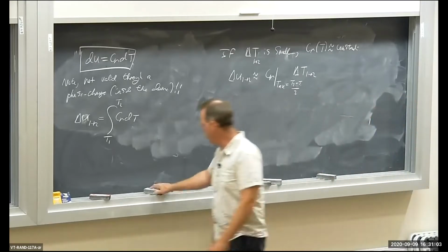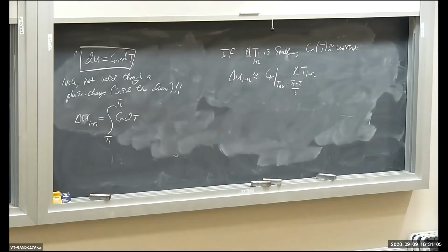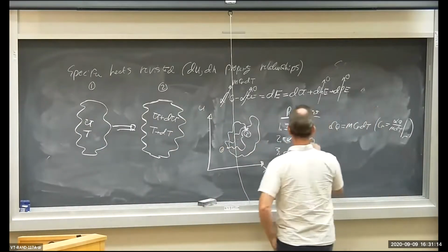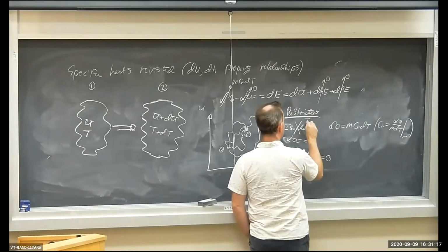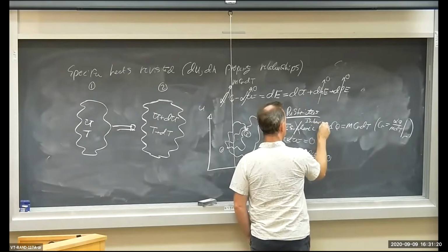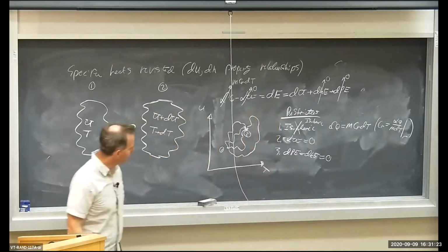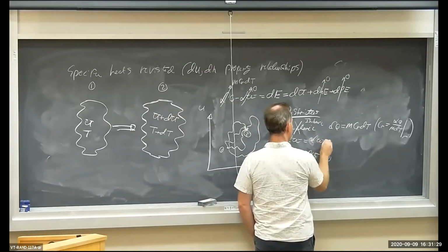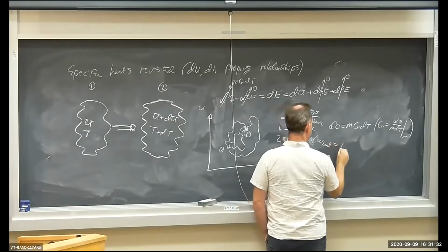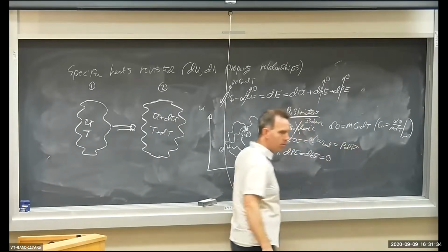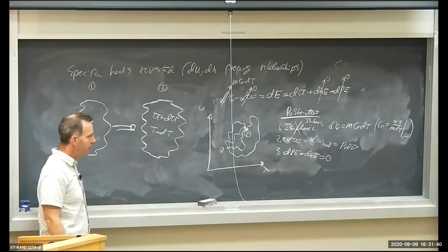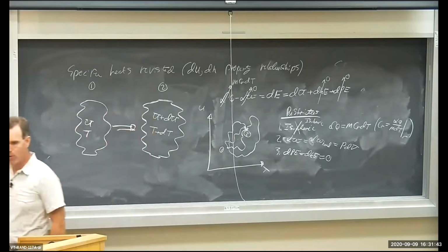Now there's one more property relationship. I'm not going to go through the derivation here, but I will make it plausible. If instead we do an isobaric process, then the work is equal to the boundary work, which is equal to P dV. And what I get instead is another property relationship for enthalpy.